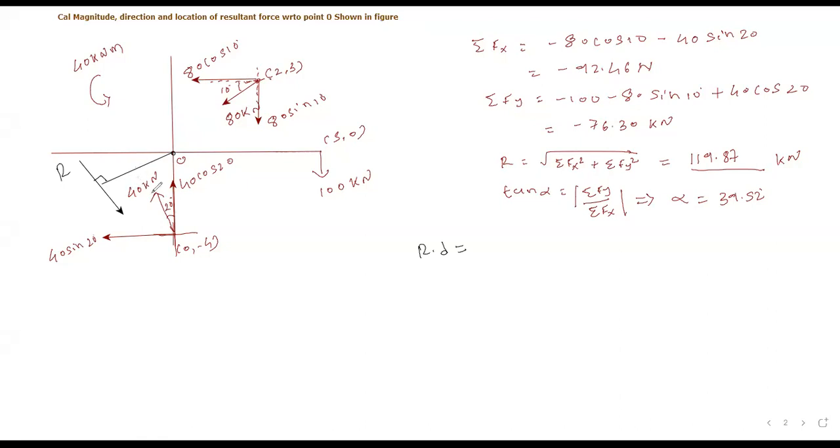I hope it is clear. Okay? So again same rule. Left side anti-clockwise positive, right side clockwise positive, anti-clockwise negative. Starting from 100 kN force in data given quadrant system 50. So can I say that this x distance is 5 meters? So 100 into 5 clockwise moment. Yes or no? 100 into 5 clockwise moment. Clockwise, so positive.